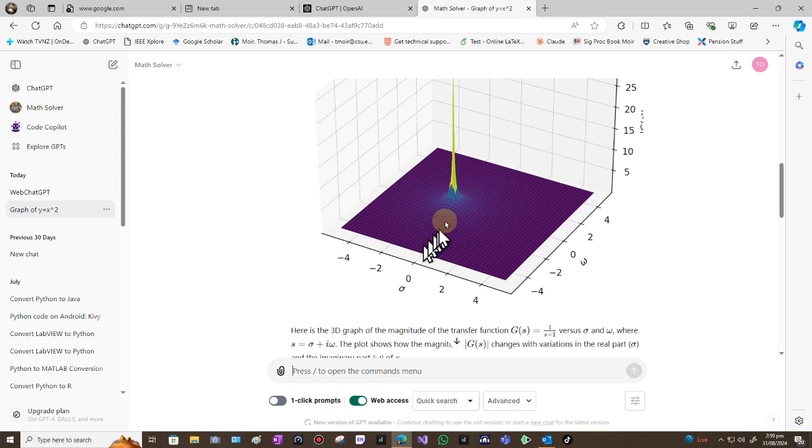This way down the center, that's j omega. If you want the frequency response, it's down the center. There's no resonance, but I know there's a resonance there, but that's at a complex frequency, so you don't see that because you're operating here, and so you don't see any overshoot in the frequency response. It's pretty flat actually, and although you can't see it, it just rolls down like a typical first